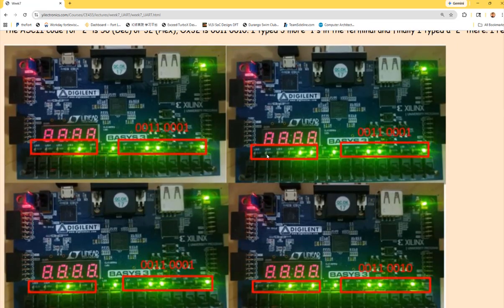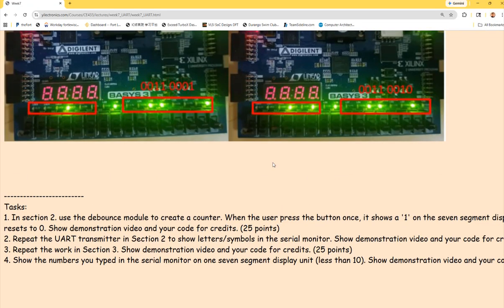See? And 11, 100, and 101. It just keeps incrementing by 1 until it reaches the maximum, and then it resets to 0. So it's just a counter to show you how many bytes have been received by the RX module. So these are the data, the parity bit, error bit, and counter. Okay, it's a counter. That's everything about the RX module.